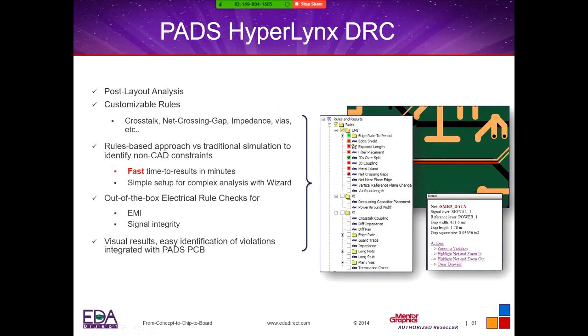Or maybe you've got too many vias on a clock line, for example. Or you've got copper that's floating in the area causing an island that might cause some problems. Or there might be stub links. So this allows you to go in and check all the different signal integrity problems that you might have on your design, more of a DRC check for you as well.